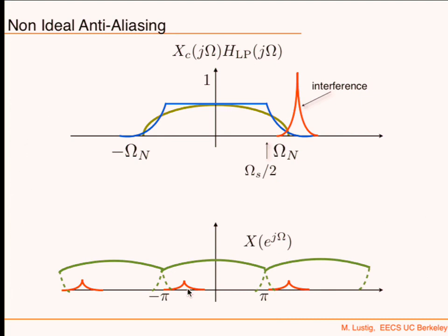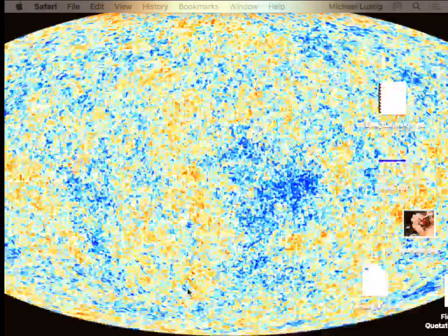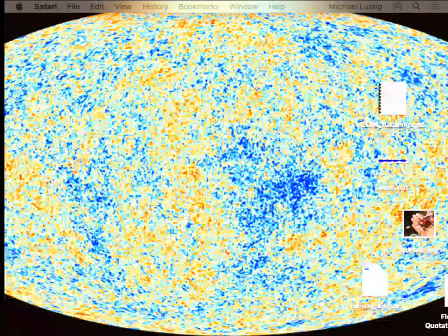The cool thing about DSP is that one thing one could do is oversample a little bit. Then you've still got some aliasing going on, and this weighting, but in the digital domain, you can correct for a lot of those effects. You can correct for the phase, you can correct for the magnitude, and so on and so forth. That makes this much more powerful than any other system. So you can trade off the quality of the receive chain by just oversampling, and we're going to talk about that later in class. I want to do this demo.